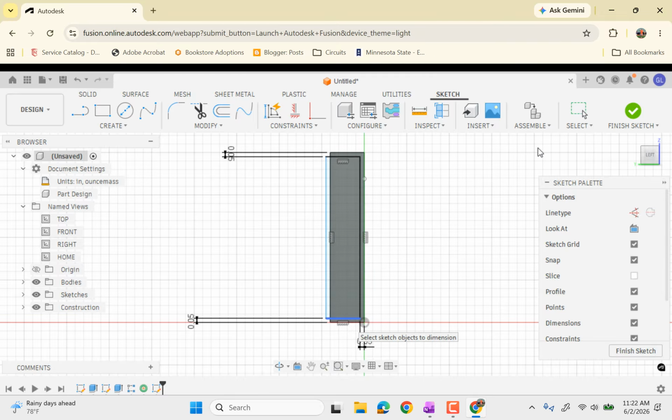So instead, I'm just going to specify the length of this, which is going to be, so we know that the whole width is 0.5, and we want to subtract 0.05 from one side and 0.05 from the other side. So I'm going to make this 0.4. Oh, no, it's not 0.5, it's 0.4. So I'm going to make this 0.3. There we go. So now all those distances from the edge to the rectangle we're making are 0.05.